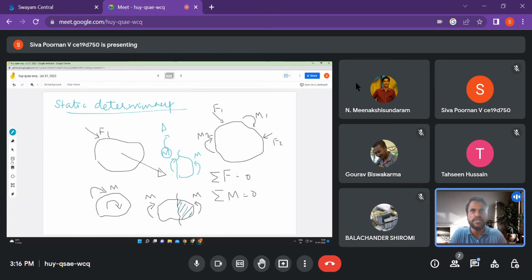And we can easily compare it with force and axial force or shear force, right? So the same situation happens when we talk about forces or axial forces or shear forces. So when we talk about forces, this is a total force onto a structure. So this is a net force on a structure. But if you have two equal and opposite forces, the net force is zero, but there will be a net axial force. So axial force is internal, and when we talk just about force, we talk about the external force, and that is what is coming from external objects. Okay, fine. I think this should be clear.